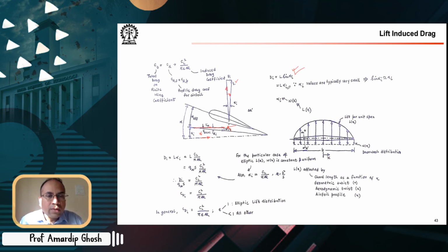For that relative wind, my lift vector is rho infinity V infinity, because V local and V infinity are almost the same in magnitude. That W is really small. So my lift is not changing much, but it is rotating by an angle alpha I. This is my new direction of lift, normal to the local relative wind, which is a superimposition of W and V infinity.